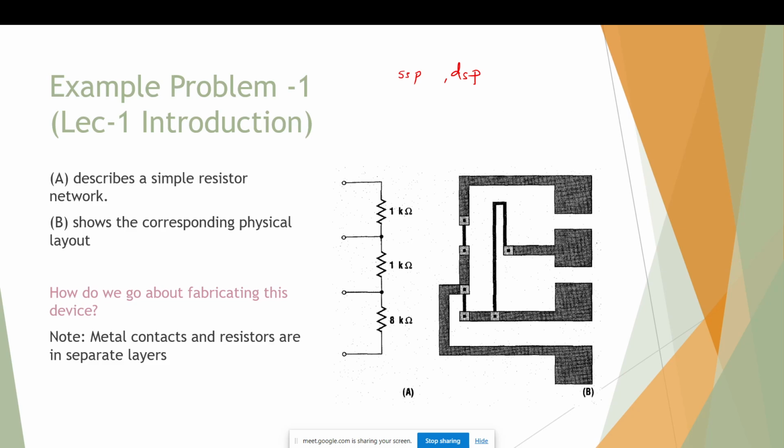Sometimes you have to worry about the backside roughness, like if you're using some sophisticated lithography tool in which the vacuum might not form correctly if the backside is too rough. In that case, even though you use a single side polish, you check the backside roughness; otherwise that is fine.